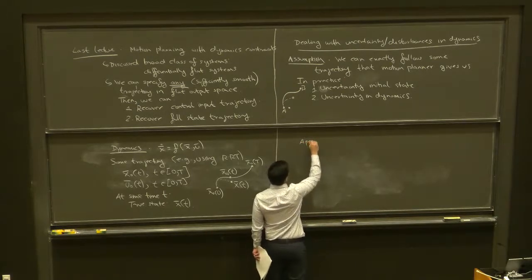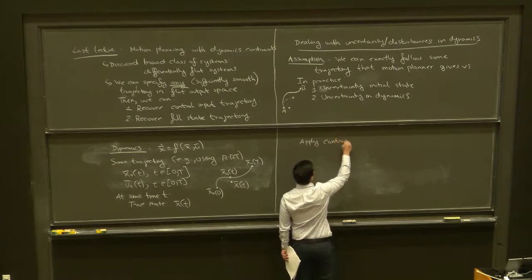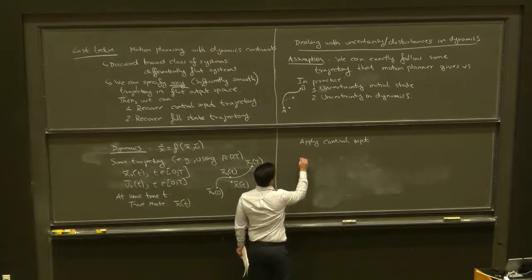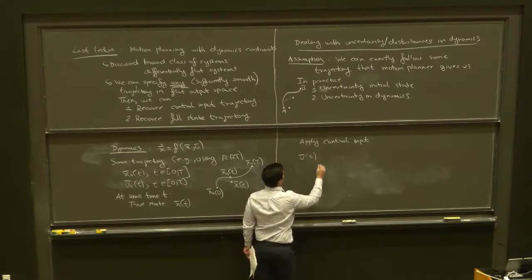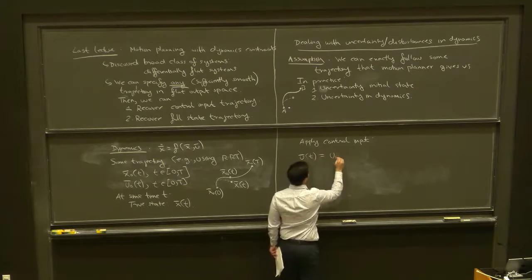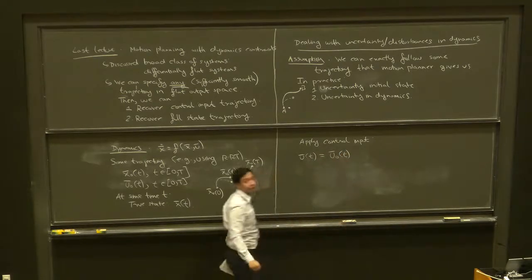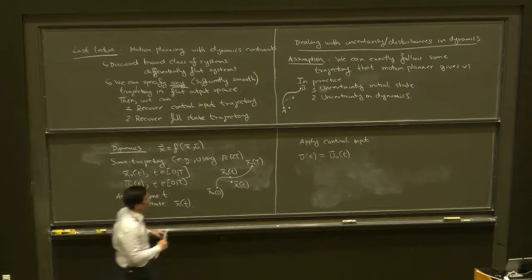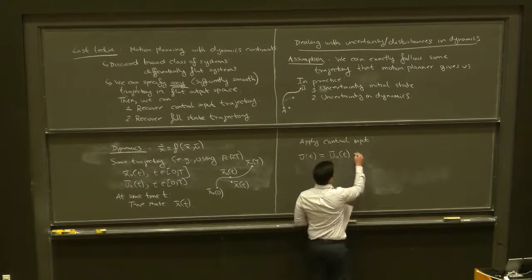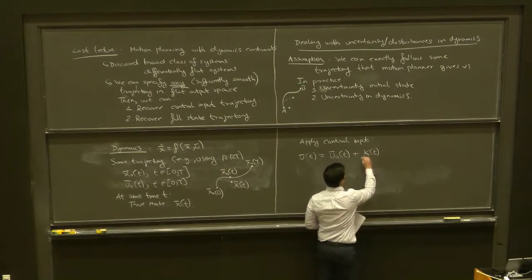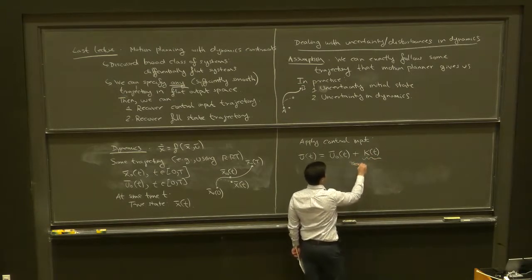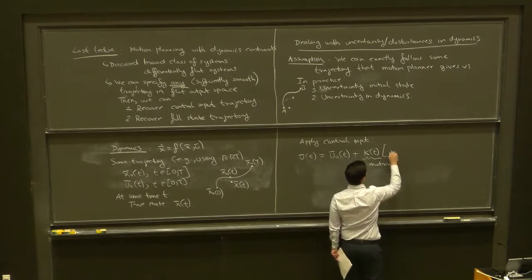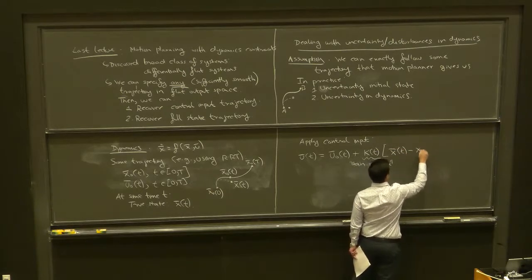So we'll apply a control input of the following form. So u, the control input at time t, is going to be the nominal control input that came from our trajectory planning, motion planning algorithm. That's this term over here, plus some matrix, this is the gain matrix again, times x of t minus x0 of t.